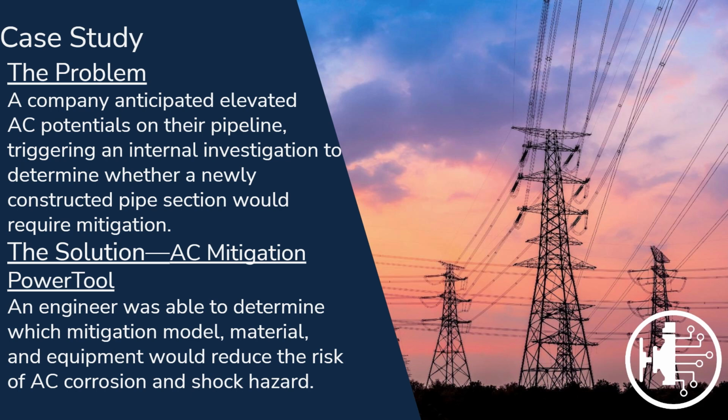We always worried about DC interference, from rail systems, and of course from other pipeline systems. But how about solar systems? How about these miles or kilometers of solar systems that are laid out? And how are they grounded or not grounded? Or are they using the ground as a return, a negative return?